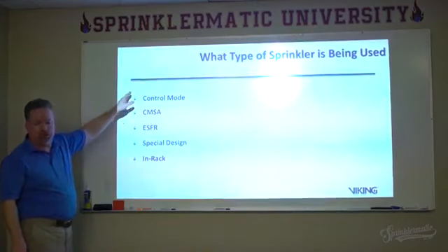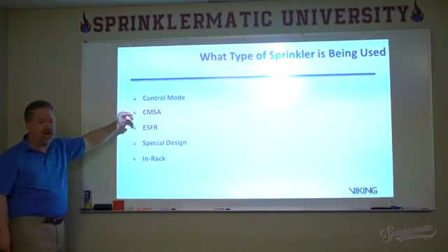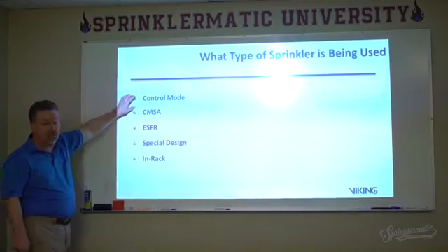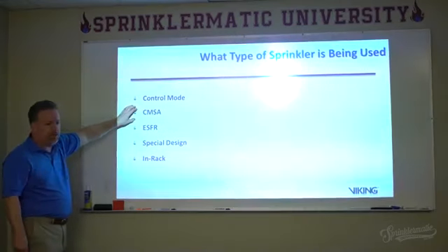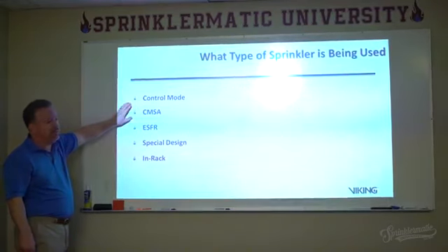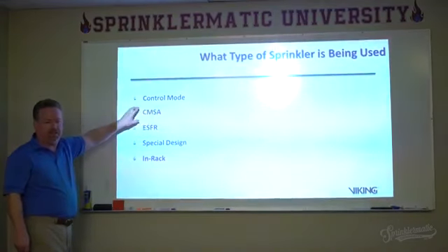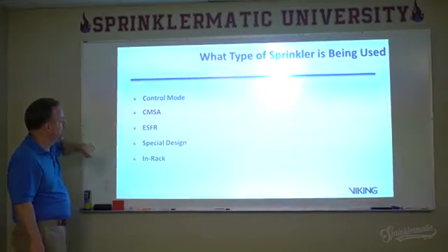Am I going to use a control mode sprinkler, a standard spray control mode sprinkler? Or maybe a larger orifice control mode sprinkler? Am I going to use what we call a CMSA? Now CMSA means control mode specific application.